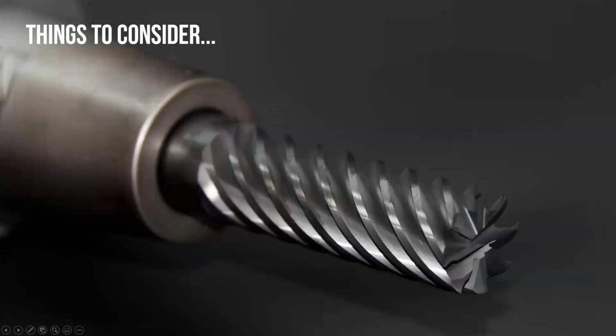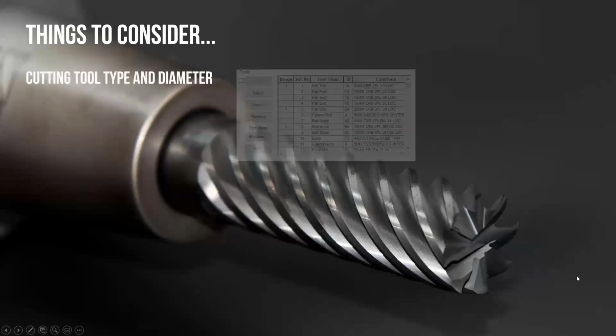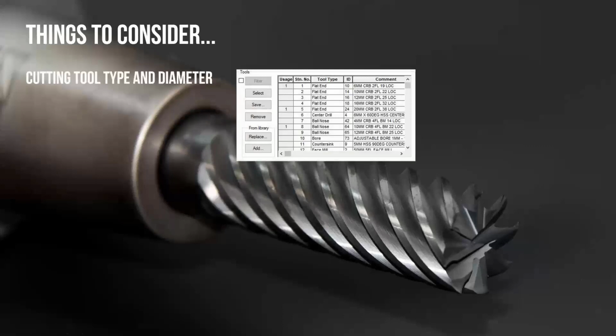So some things to consider, and this is what we're all here for in the webinar. When optimizing your finishing operations, there are a few things to keep in mind. Number one is going to be the cutting tool type and diameter. This is going to include flat, bull nose, ball nose end mills, or even special tools such as a lollipop cutter, which are all available from the tool database, the tool crib, or even from the SOLIDWORKS CAM tools tree.